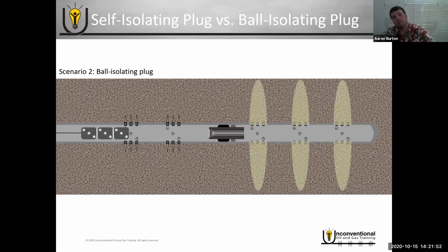So with the ball isolating plug, because you don't have that instant isolation, that gives you the ability to re-enter the wellbore, or at least to pump through the wellbore, so that you can recover quickly from the perforation gun not firing.